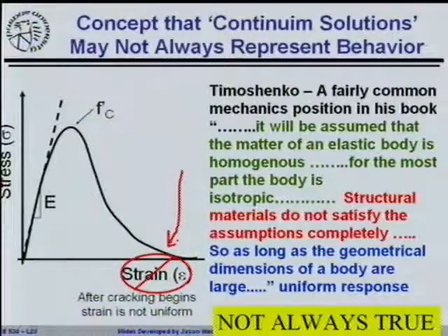All right? I understand that some of these concepts are not easy and some of these are going to take a little bit of thought. But the idea is you can only use strain when the material is displacing uniformly. When you have preferential displacement in one region, and in this particular case we're talking about displacement in the crack region of the concrete, all of a sudden the concept of strain becomes very, very muddy, because how do you quantify that strain? What gauge length do you start using to describe it? It makes the entire thing a little bit more complicated.